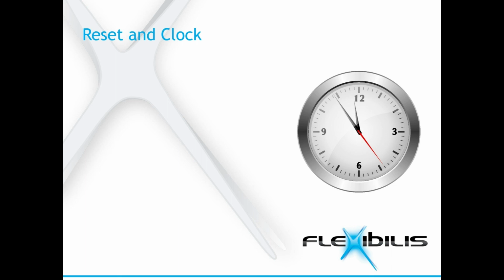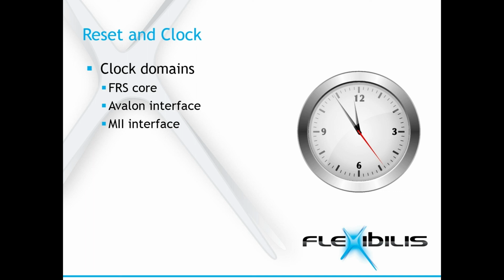FRS has separate clock domains for the FRS core, for Avalon interface, and for the transmit and the receive sides of the MII interfaces. Typically, there is one oscillator on the board. The clocks needed by FRS and by the other FPGA blocks are generated at the FPGA with PLLs. Exception to this is the Ethernet receive clocks that come from the line in case of external Ethernet interface.